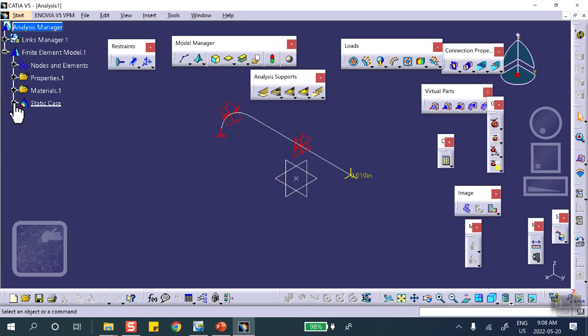Now, look at what I did there. I followed the symmetry rule. That is correct. Rotation about Z was free. Displacement was 0. Rotation was free. You followed the correct process. But because of the nature of the problem, if rotation about Z is actually free, then this can go like that. It has nothing to do with the symmetry. The symmetry we did right. But because rotation about Z is actually free, it can move as a rigid body like this. And you can see that actually. If you look at this, you will see that it pivots about that.